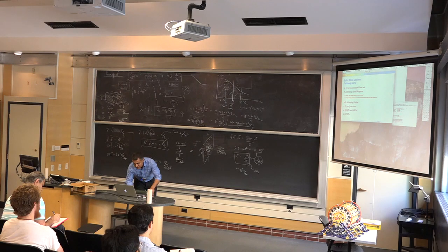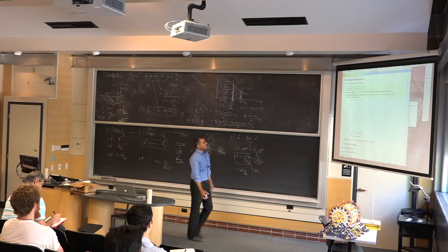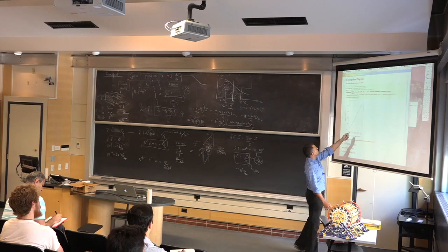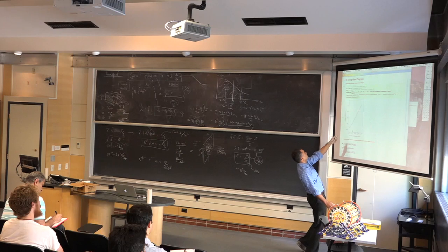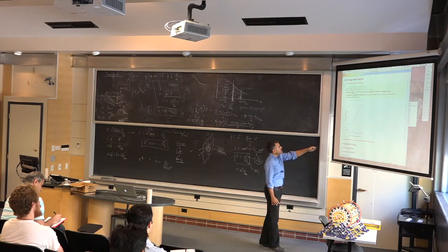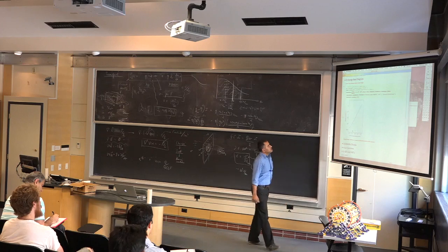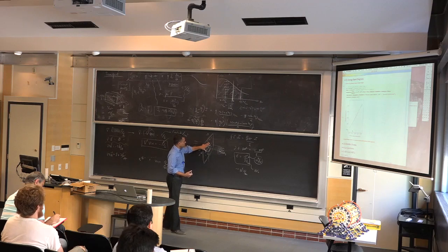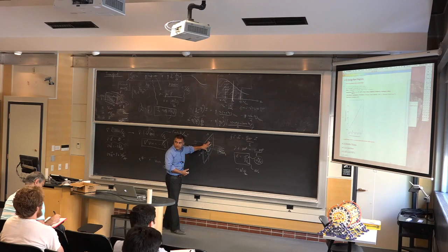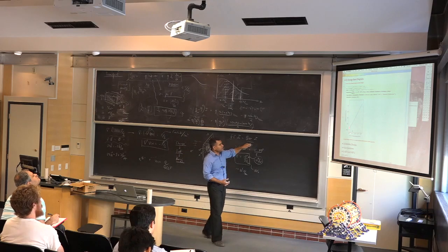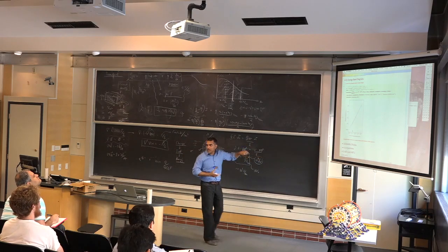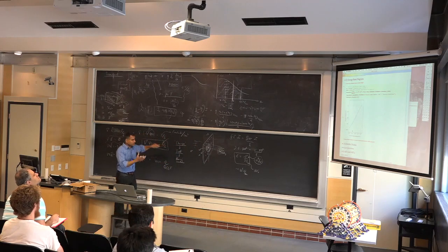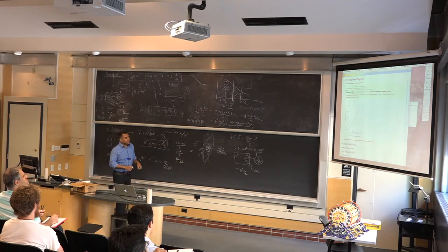What happens is actually this sort of field, because you can change these charges by many orders of magnitude. So for 10 to the power 13, it's hard to see, but it's about 10 to the power 6 volts per centimeter. 10 to the power 10, down here. And in a semiconductor, we can change the density of charges by many, many orders, which is why we can change the field by many, many orders. And the field control is typically always like that, with sheet charge density.